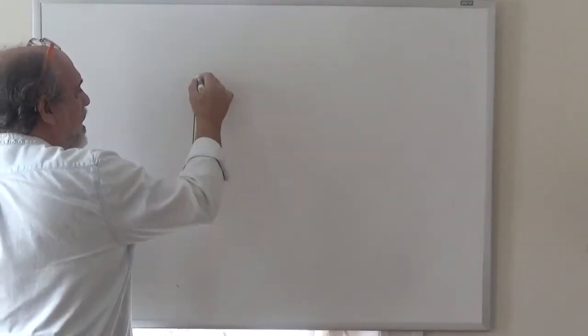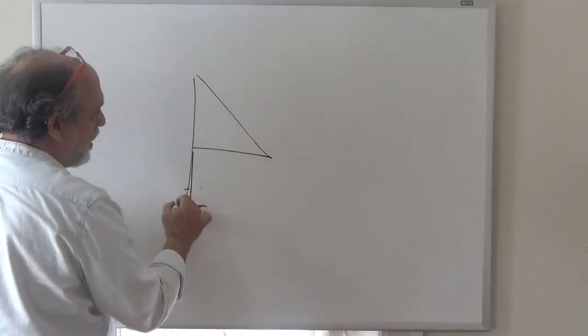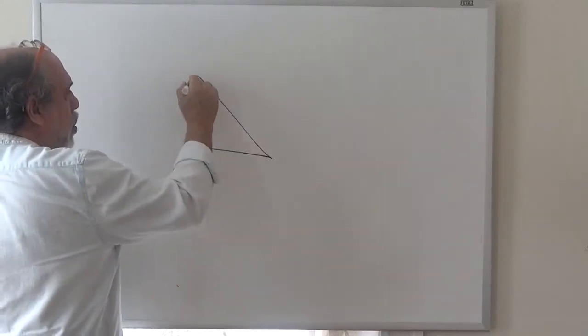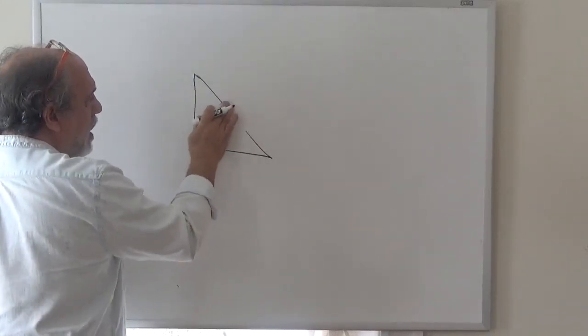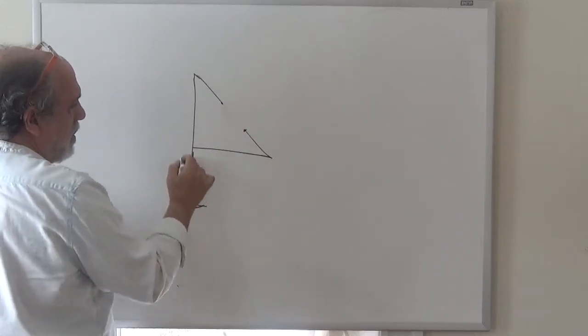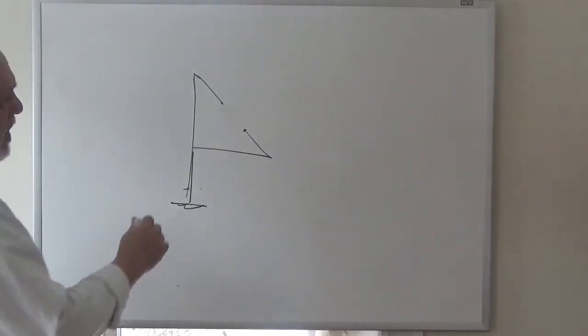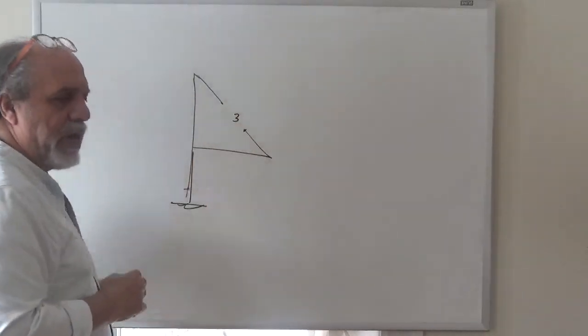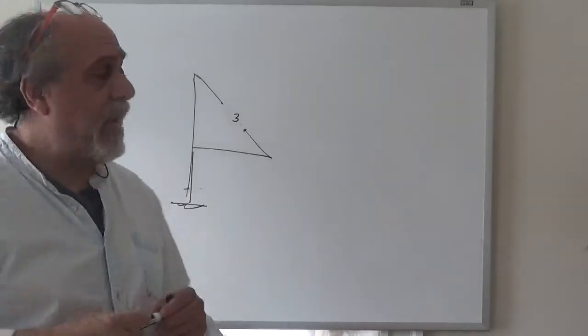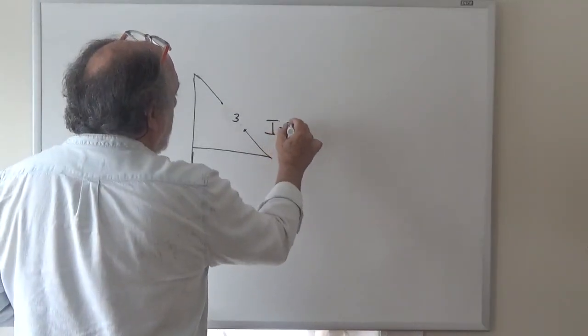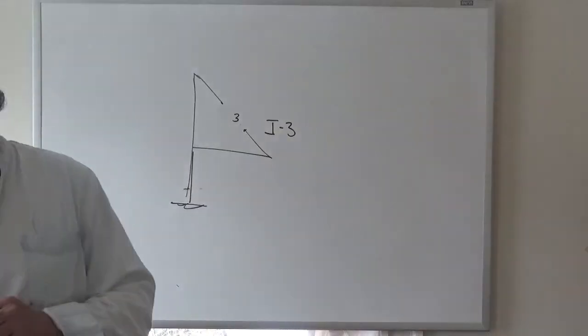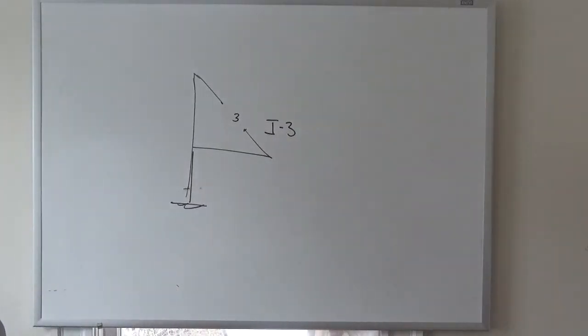And the idea of the tree makes it clear, because it's one tree, right? But trees don't do that, they're open. So you can open it up. Now that's a tree. Here's a branch, it stopped there. Here's the other branch, stopped there, right? And then when you did this, how many unknowns were there? 3. Axial, shear and moment. Therefore, that structure is I3. Okay? So that is determinacy and indeterminacy basics. All right?